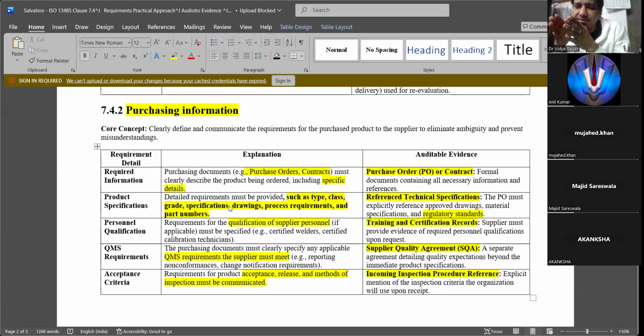Be very particular whether it's 5 plus or minus 0.5 or 0.2, or you can have a large leverage of giving 5 plus or minus 1. Then it becomes 4 to 6, or 4.8 to 5.2 if you give a small tolerance. This is very important when you give specifications.